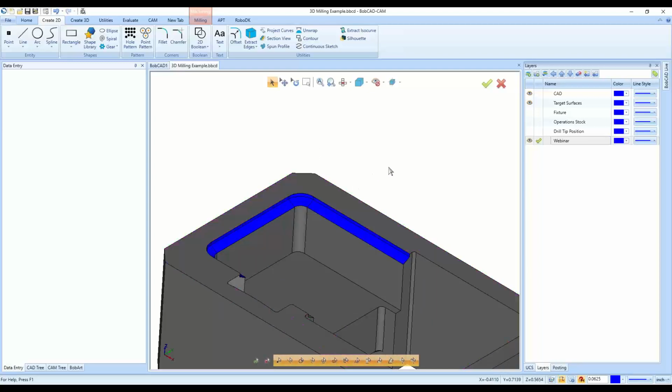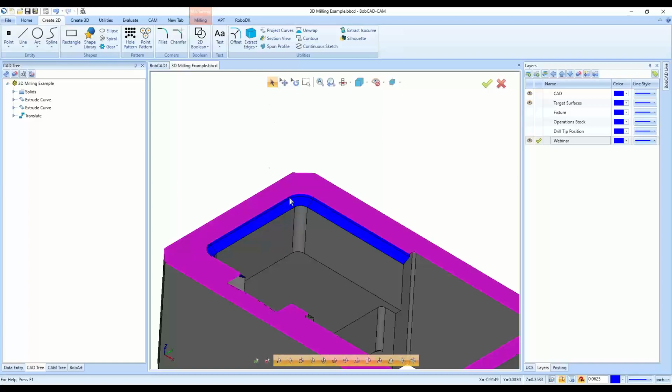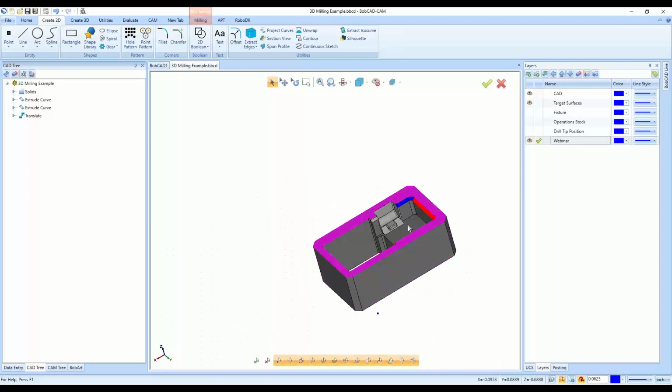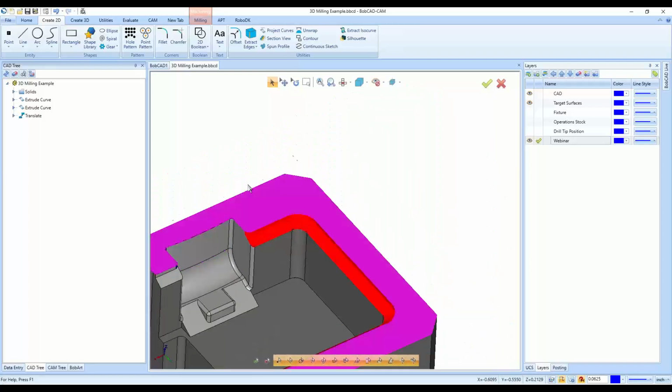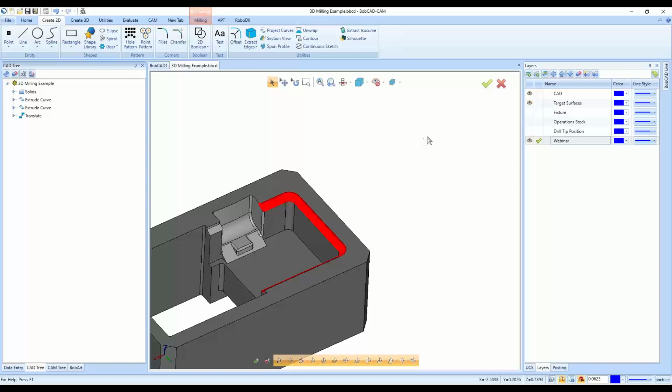And we can go here. I'm just going to right click out here and cancel everything, just in case I was in any CAD functions. I know I was in the select mode function, so I just canceled out of that. I'll go up to the top, go back into select mode, and highlight all of these surfaces. Just by clicking on each one individually, we can right click and go to modify attributes again.